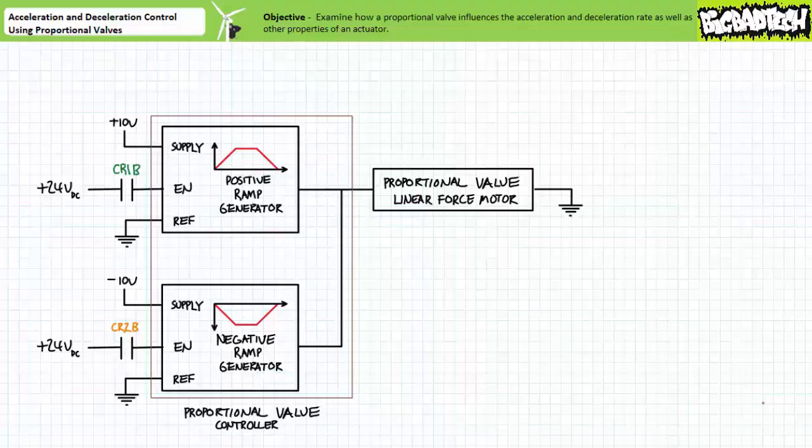Note, however, quite like the interaction between the primary hydraulic circuit and the pilot ladder logic, the limit switches being the principal examples, there exist interaction points between the pilot level ladder logic and this proportional valve controller. Notably, normally open contacts CR1B and CR2B.